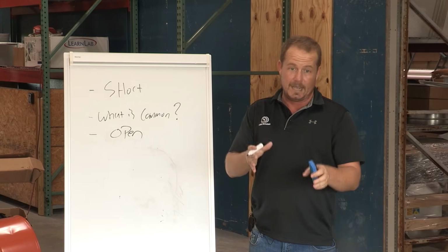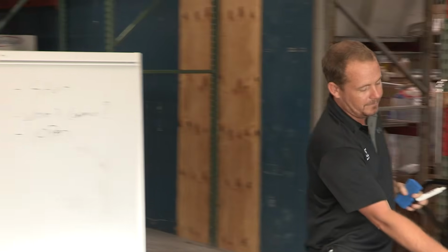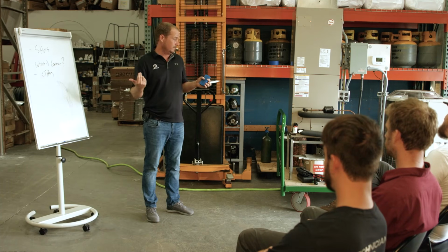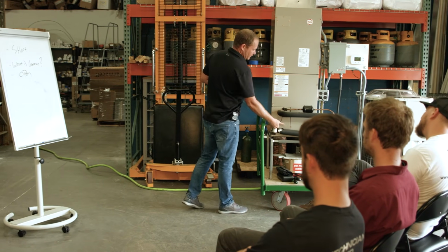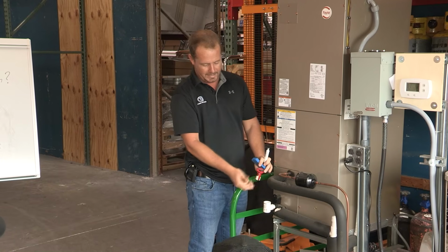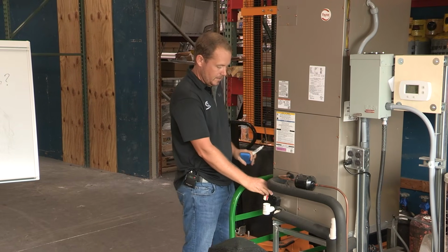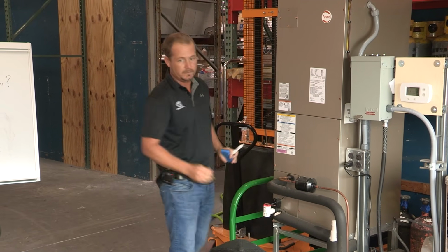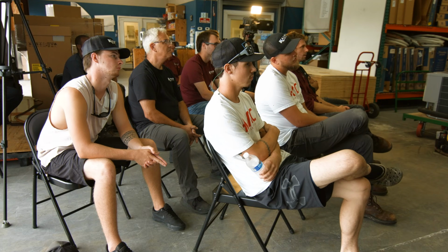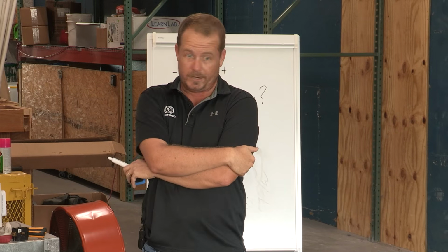That could be designed like that, but it could also be if I take this wire going to my float switch right now and I cut it. That's an open, right? If the water rises in the float switch and it trips the float, what does that do to the circuit? It opens the circuit, right? So what happens when a circuit is open? What happens to the system? Electricity stops flowing to the component. Electricity stops flowing to whatever circuit we're talking about.